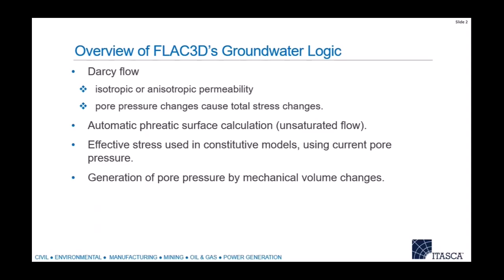You can think of that as, the cartoon in my head is that you've got like a sponge or a matrix of material filled with water, and the water is carrying some of the pressure. It can't carry any shear because water doesn't have any shear resistance. So it's carrying some of the pressure, and that reduces the pressure in the material, but it doesn't reduce the shear, and that can bring it closer to the failure surface, right?